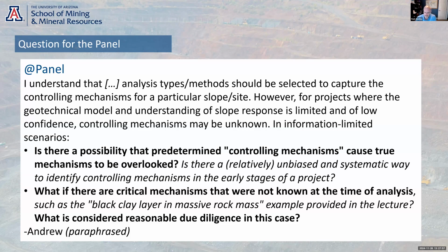So the first thing to do is go back and look at the geology and try to conceptualize what the controlling mechanisms might be, and don't rely on a model to tell you that. The model should be used to help verify your conceptual models, perhaps change your way of thinking. If the model comes up with something different, then that's something that you need to be thinking about. But first step, go back to the geology, look at the geology, conceptualize the model.